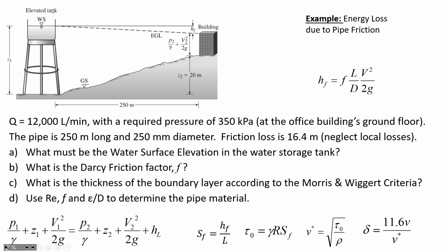That should sound familiar, since we talked a little about the related homework problem on Wednesday; you've got one similar to this for the homework assignment. We're going to do an example that illustrates how to determine the friction factor. We won't actually apply the Moody diagram, because the problem statement gives us the H sub F. So we'll be estimating the friction factor as the only unknown in the Darcy-Weisbach equation.